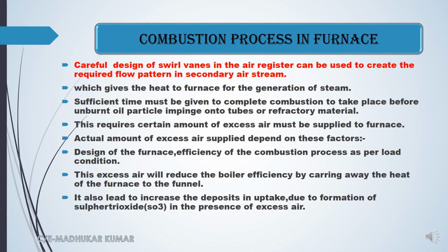The design of the furnace, and the efficiency of the combustion process as per the load condition. These are basically the three factors which decide the amount of excess air which needs to be supplied for proper combustion of fuel. This excess air will reduce the boiler efficiency to some extent, but we cannot take much chance because we need proper combustion and proper heat development for the steam generation rate.